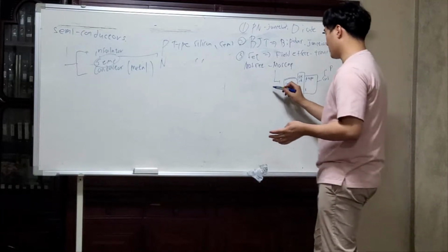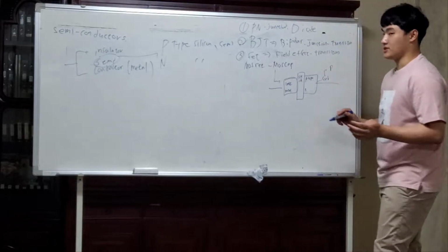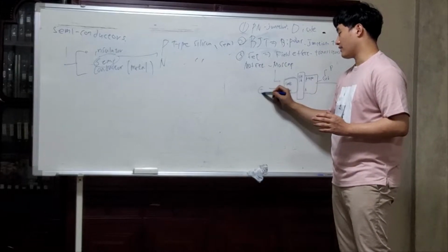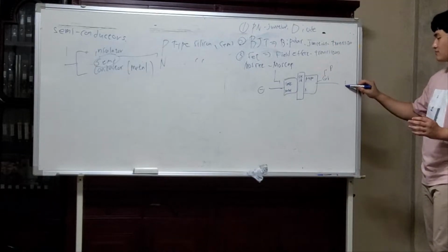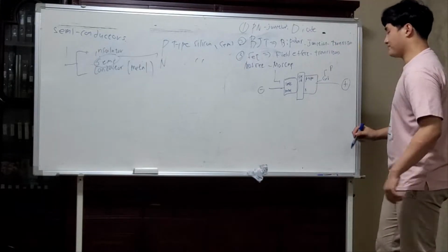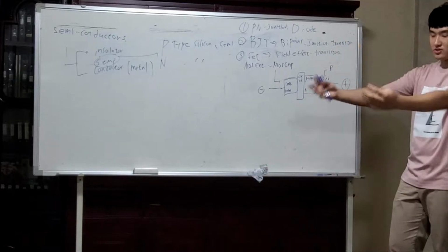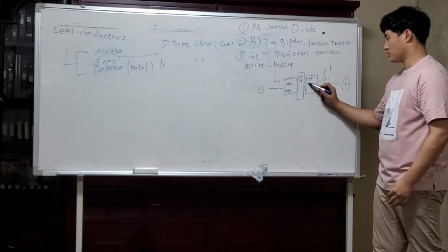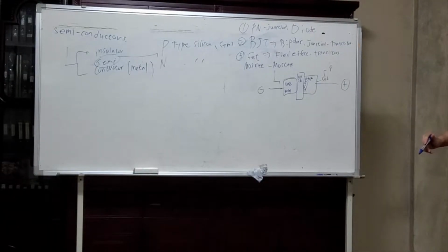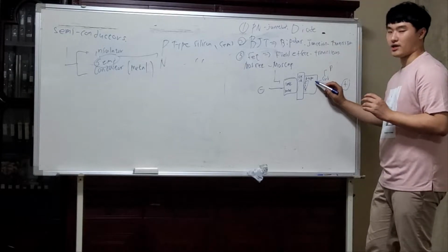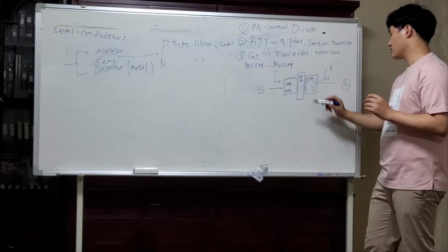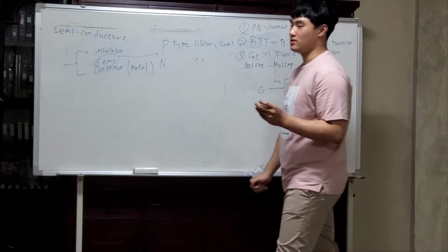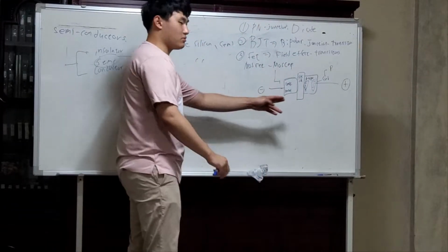Then, if we apply some voltage to the gate, a negative voltage, and for the substrate, a positive voltage, then by the attraction and repulsion, the holes will get closer to the outside. Second, the electrons will gather at the end of the substrate, but it is small, so we call it the accumulation state.